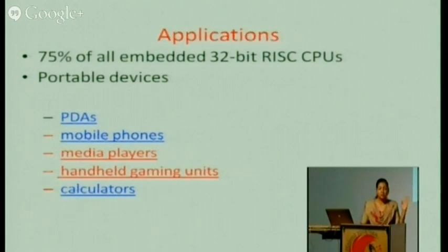Besides its own instruction set, it provides another instruction set known as the Thumb instruction set, which is 16-bit wide, right? The second one is the debug interface, which is provided with the help of the JTAG controller, that is Joint Test Action Group, available with the IEEE standard 1149.1, and this basically provides the ISP feature, that is the in-system programmable feature. What is the precise definition of ISP? That is the ability to reconfigure the logic and the functionality of the device. Both the logic and the functionality of the device can be reconfigured with the help of the ISP feature, which is provided by the JTAG.